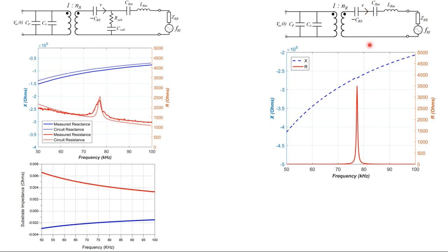If you have a thick or rigid substrate, it's a very large impedance, so you have open circuit conditions across the transduction force. So you can see a very high Q. The frequencies in both cases are the same, but you see a very high Q resonance, which is not the case if you have a thin backing.